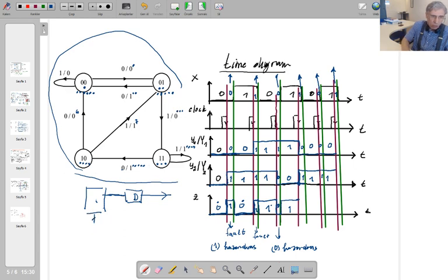So this works with a clock pulse on the negative edge. This clock is also connected to that D memory element. This is the negative edge again. So you've got the input here, right? When this clock pulse comes, according to the input and present state, you're going to get Z here.